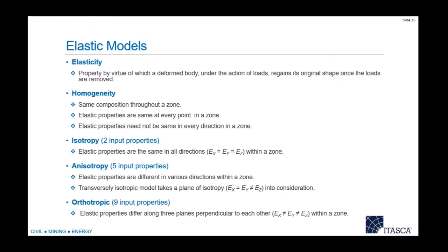Even though on the surface, the thought of these transversely isotropic elastic models is kind of cool, because you could have some sort of bedded material, in reality, people don't use them that often because they don't fail. They're elastic. In reality, if you've got a bedded clay or something like that, it's probably failing. So it's cool on the surface, but it's probably not that useful in practice.